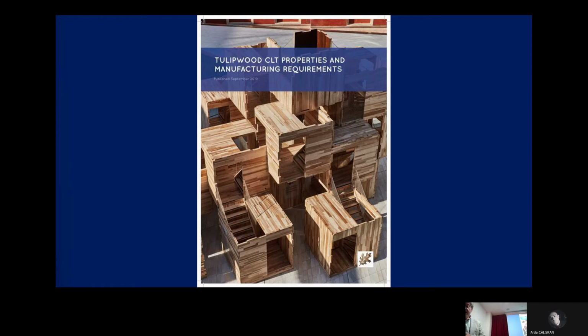From that project, we were able to make some panels for testing. So we tested them at Edinburgh Napier University to get some structural data on how these panels performed structurally in flatwise bending, edgewise bending, to compare and contrast the properties of this material against published data for conventional, say, softwood published data from 2 softwood producers of CLT. And they're all in this document here, which is available on the website. And the results were very, very positive.